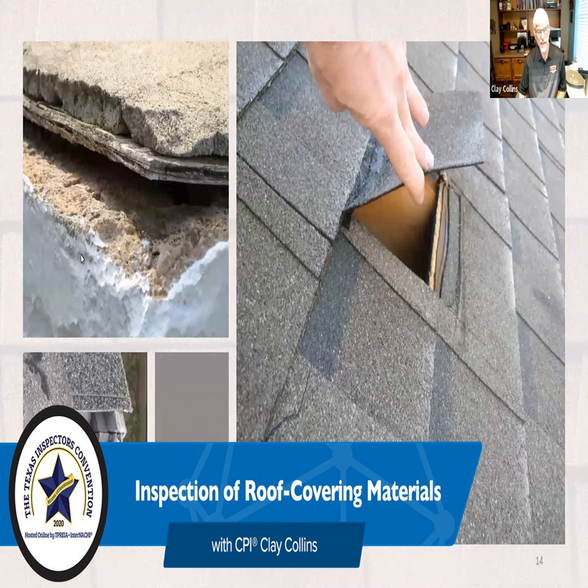Wind is going to throw things into the roof cover. Wind is going to take the granules, the aggregate, off the roof cover. And wind will severely impact ridges and hips, because that's where it changes directions as it goes across that portion of the roof cover.